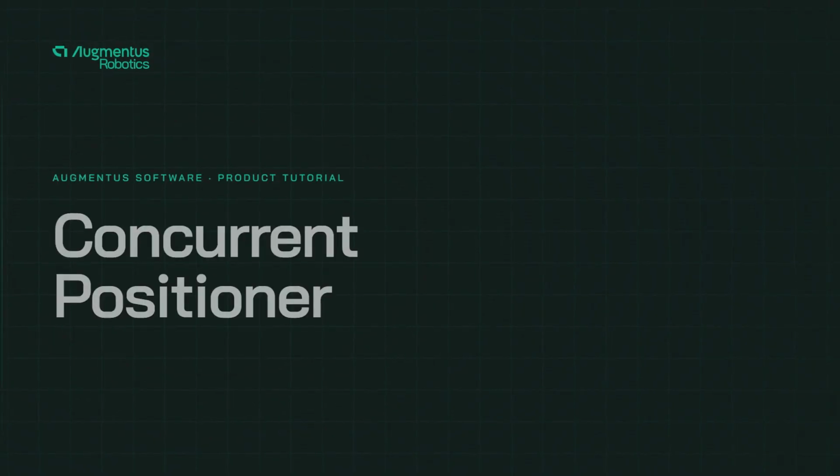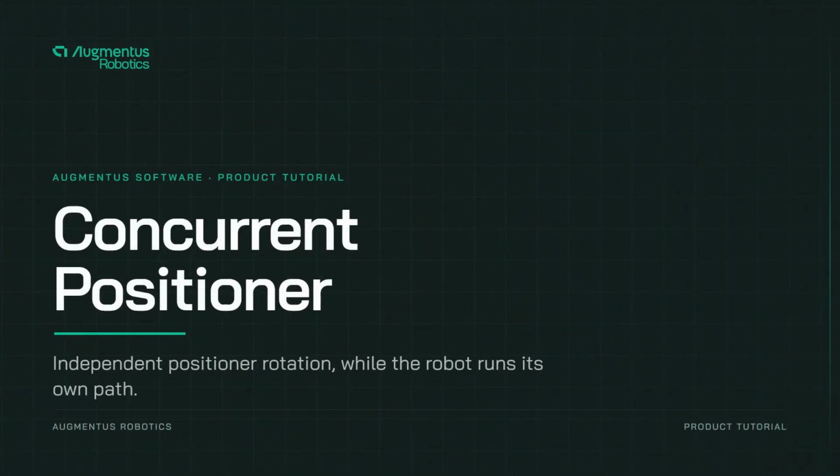And that's the concurrent positioner. Wrap your path in the module, set the axis, mode, and speed, and the workpiece turns on its own while the robot follows its path, ready for continuous processes like thermal spray and shot peening.